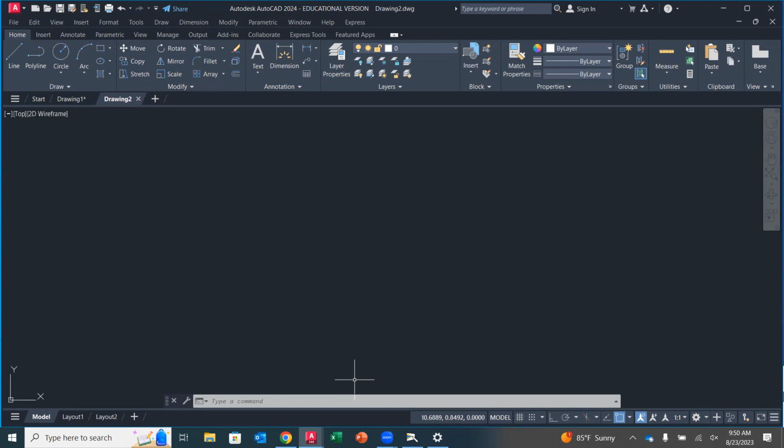All right. So now what we're going to do is we're in AutoCAD and I want to start drawing. Now, since I'm going to start at that lower left-hand corner, that's going to be my 0, 0. So I'm going to start my line command, and it's going to ask me, where do you want to start? Now, I could randomly start picking a point. It's totally fine. But since I've got coordinates here that I can directly enter from my drawing, why not start my first point in that lower left-hand corner at 0, 0? Okay, so I'm simply going to key in 0, 0, enter.